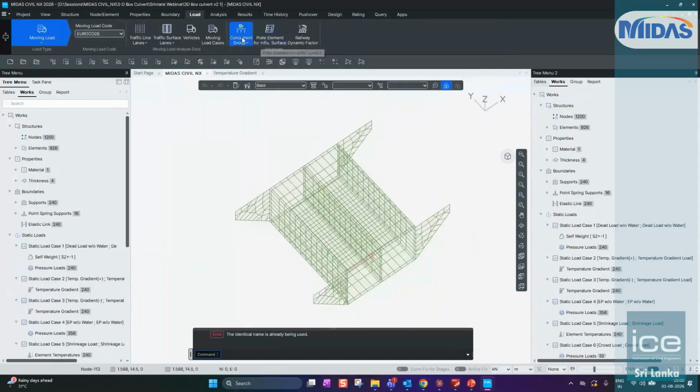We also have the option of looking at the forces at the concurrent groups. For example, you have multiple supports, but you want to know that when I'm having the maximum value at this particular support, what is the force on the other supports at the same concurrent reactions? So when fz is maximum at this particular node, what is the value of fz for the other nodes as well as the other values? So that is the purpose of concurrent groups.